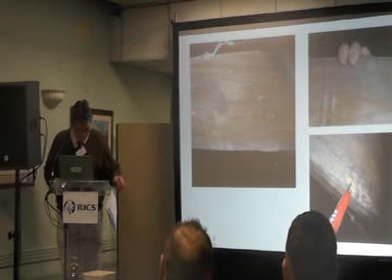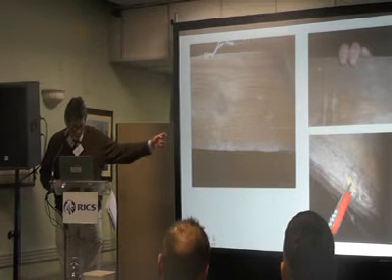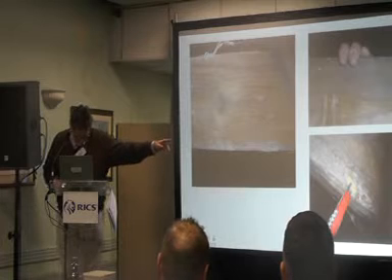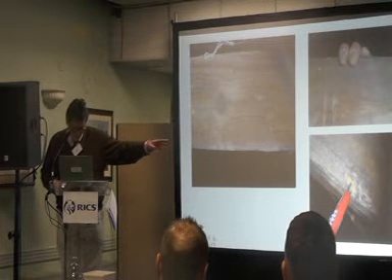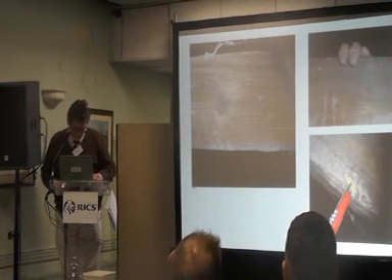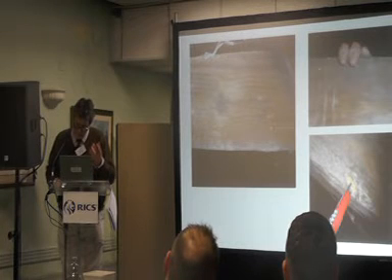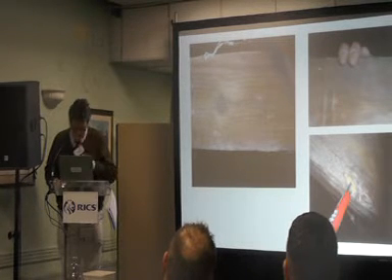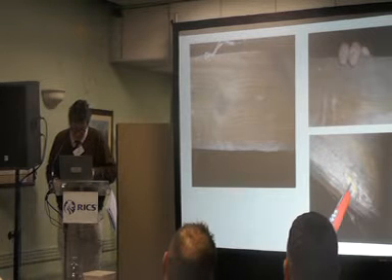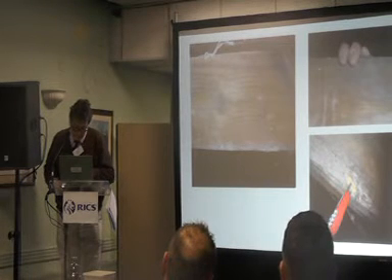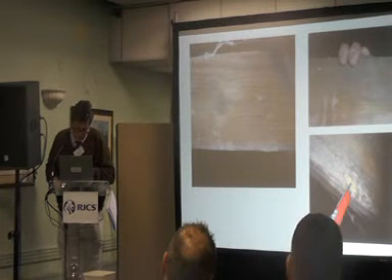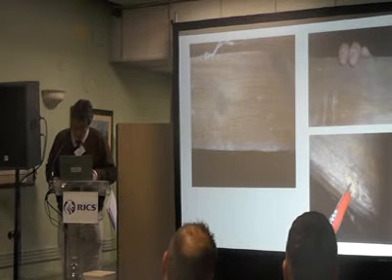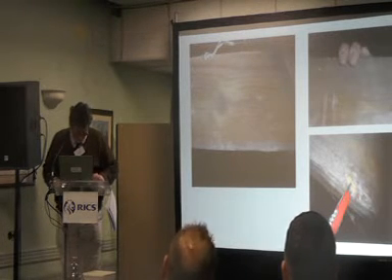Onto some pictures. We've got Deathwatch beetle on this side. We've got common furniture beetle on the other side, my assistant's fingers. At the bottom picture, timber that's been damaged, but the heart of it's still fine. It's the same beam as the fingers are on. Those furniture beetles are not active, and we recommended no particular treatment. We're not replacing the timbers there.